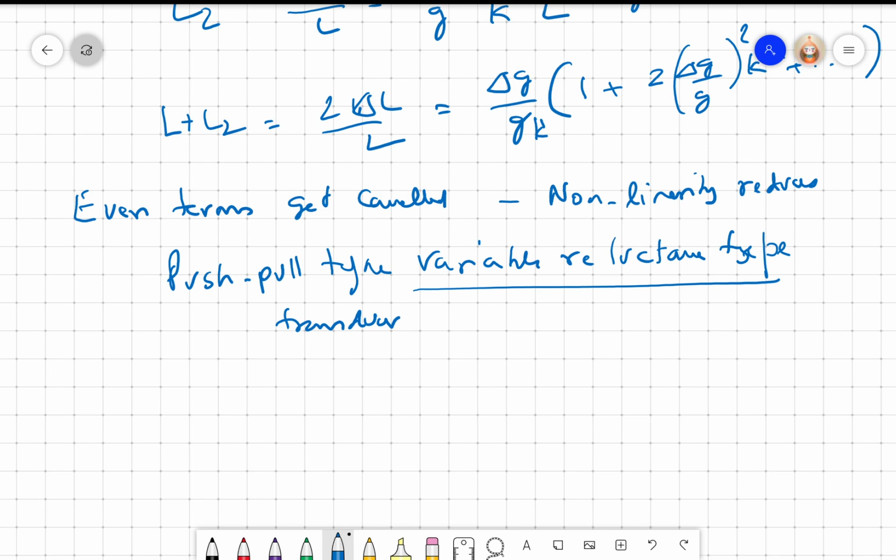The main advantage is, if I look at it, what is there in the transducer? I have iron. Of course, we don't use just iron. We use either silicon steel or nowadays nickel iron, right? Nickel and iron, whatever it is, a magnetic material, and copper, the wire that we wind, right? And what will happen to them when it ages? Nothing. If I ensure that the iron doesn't get rusted, I take enough protection.